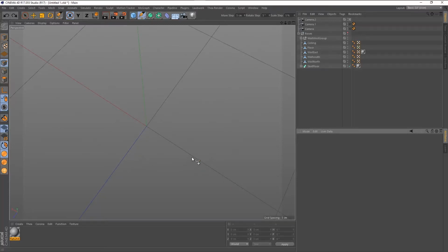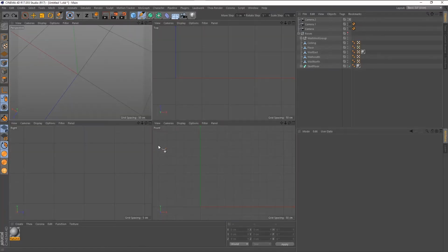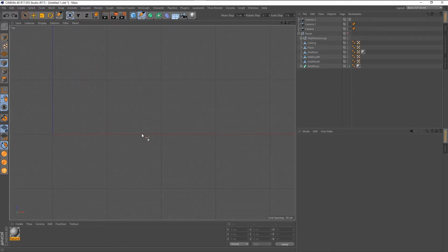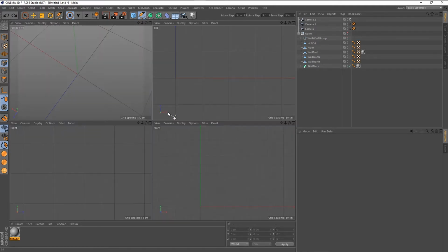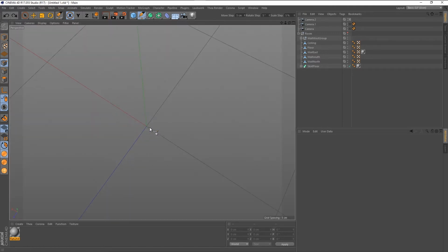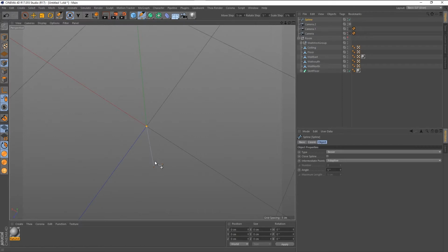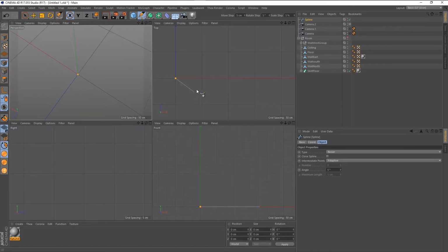Okay, so I figured out the pen tool problem I was having before. I was doing everything right except that I was drawing in the plan view, and God only knows why Cinema 4D made it. What I wanted to do was try to snap to this axis when I got close to it, but it wasn't working. And so I'm going to hit Control Z. But if I'm in perspective view and I'm close to that axis, I just click, it works. Why doesn't it work when I'm in plan view?